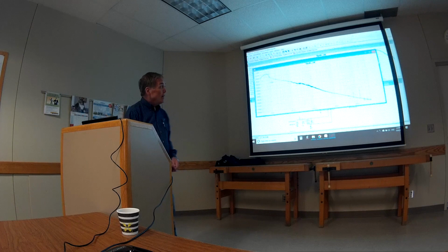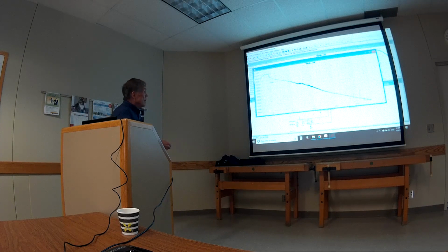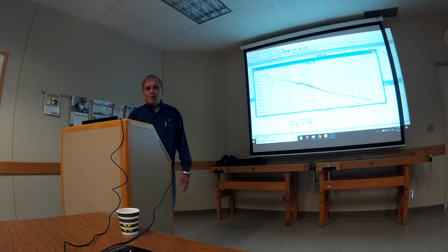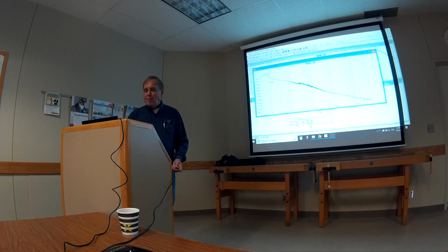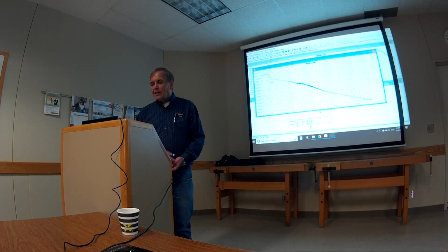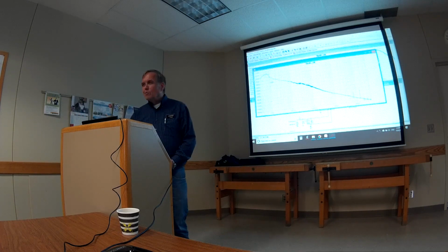And you can see down here, this is 1 kilohertz, 10, 9, 8, 7, 6,500, 6,000. So that shows you that the crystal worked at that frequency, and you know the local oscillator worked, and the difference was what we came up with, and it's very close to 600. And you can see it all in the FFT display.